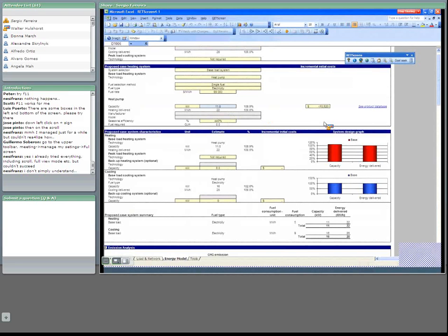It depends also on the size. Of course, when you have an air heat pump, you will have to take care of the outside temperature, and if it goes very low, then you could have some troubles. Because at very low temperature, there is still some heat within the air, but it's very limited, of course, when the temperature drops. So in that case, you will need another type of heat pump, for instance, the types we have mentioned before.